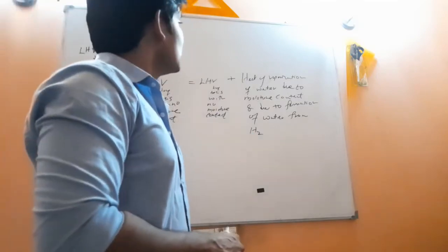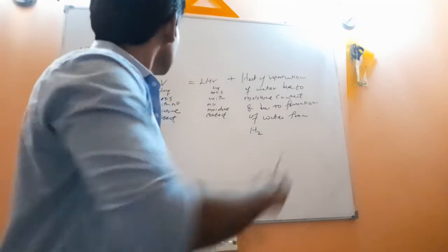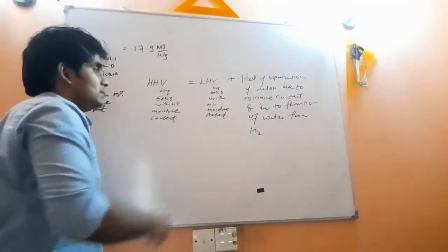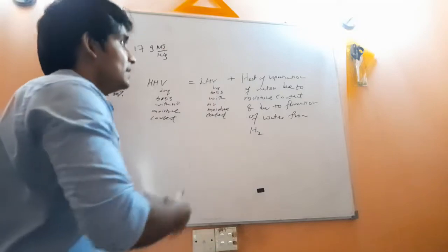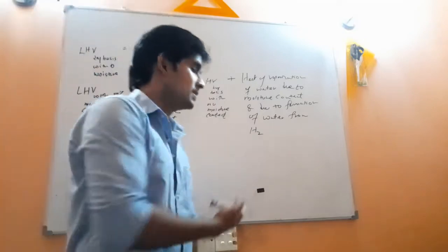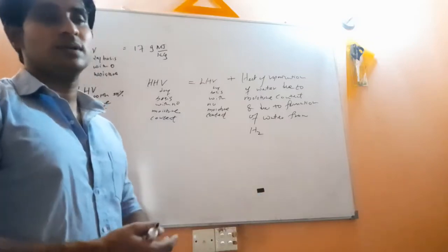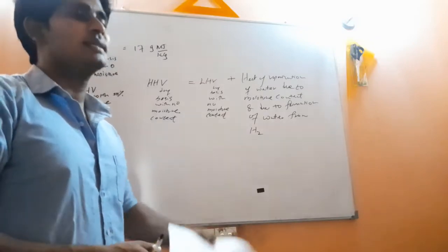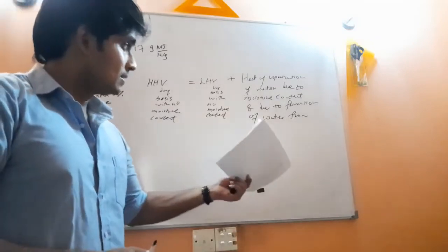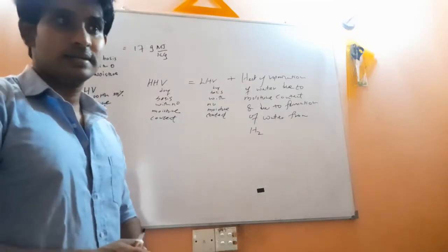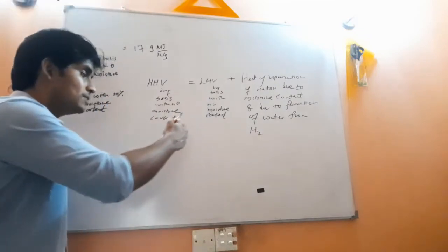So the higher heating value equals the lower heating value plus the heat of vaporization of water because of the moisture content of the fuel plus the water that is formed due to the hydrogen that is included in the fuel.